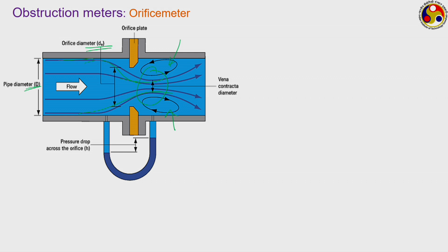So, in case of an orifice meter, we generally go for the measurement based upon the CV. Like if we just see this particular configuration where one tapping is put in this particular position 1 and other tapping is put in this vena contracta position, say position C, then we can apply the Bernoulli's equation to write as P1 upon rho plus V1 square by 2 is equal to Pc upon rho plus Vc square by 2, assuming they to be having at the same elevation.